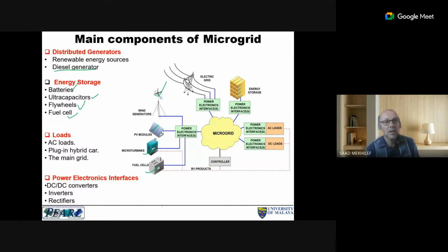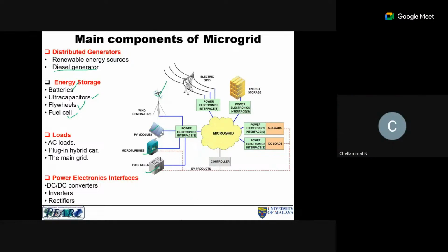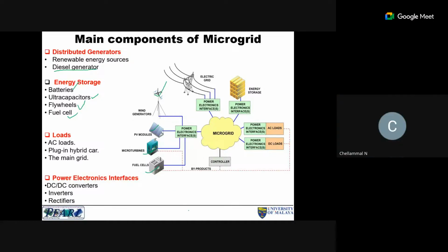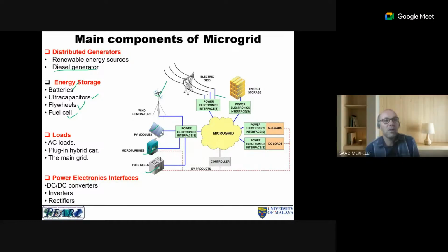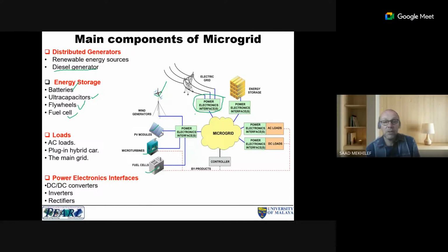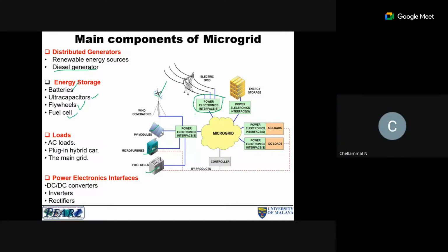And some of these power electronics are bidirectional. Can you give me an example of a location where these power electronics have to be a bidirectional device? Battery charging. Wherever you have energy storage. Yes, storage, you need to have a bidirectional. How about from grid to energy storage, from PV to energy storage? The grid also has to be bidirectional. PV to grid?